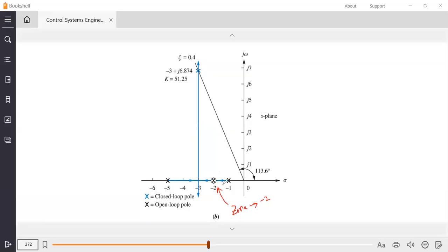So the segment right now is just between -1 and -5, exactly in the middle. You are going to have one vertical line going upwards and one going downwards, and the intersection with the zeta line gives you a new point. Then we can check the new settling time, peak time and percentage overshoot.